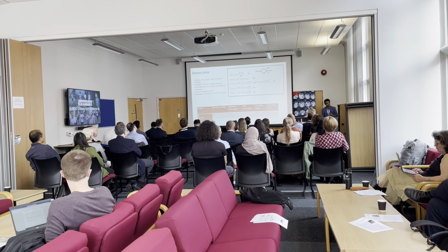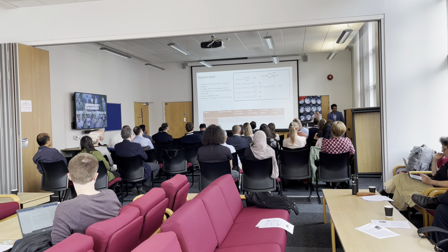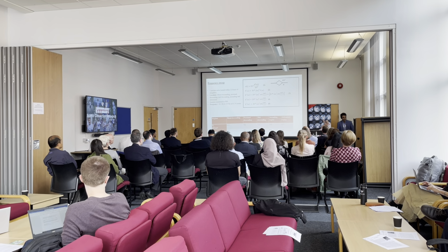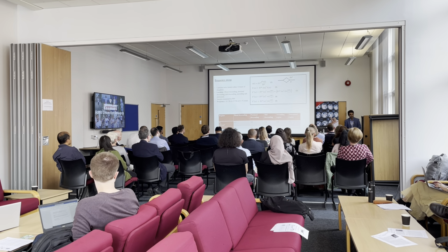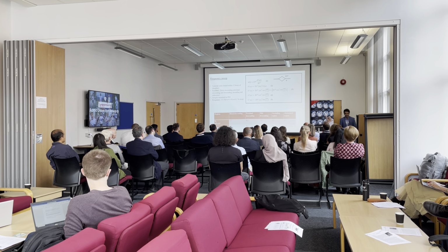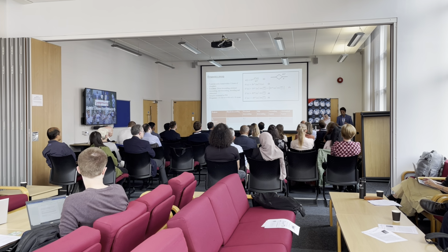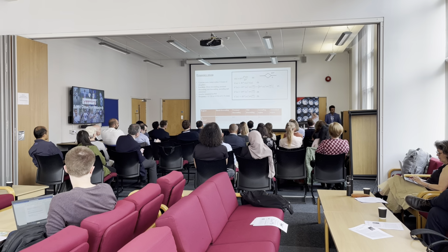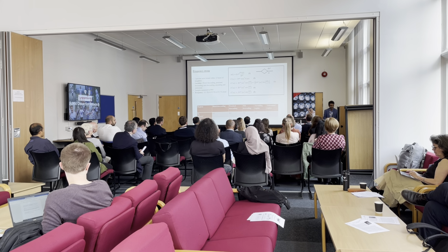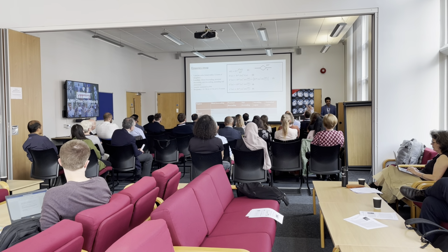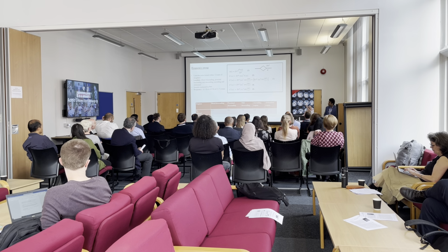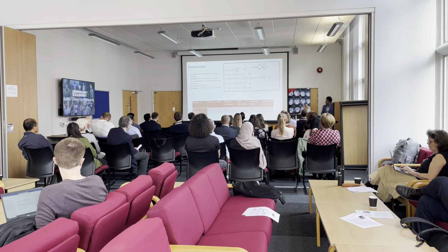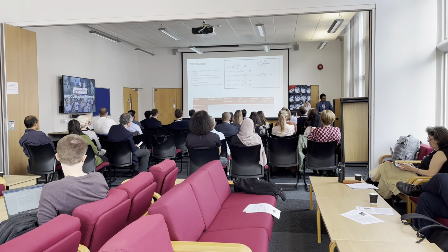here, if you substitute the value of alpha equals 0 in this equation, the springpot changes to that of the spring. At alpha equals 1, the springpot changes to that of the dashpot, which implies that this element has properties intermediate between that of the spring and the dashpot. Once we convert this equation from time domain to frequency domain, we can obtain one equation for the storage modulus, which is equation number 4, and another for the loss modulus, which is equation number 5.